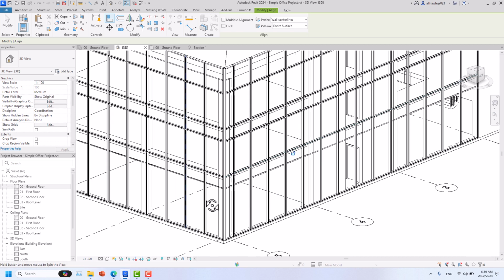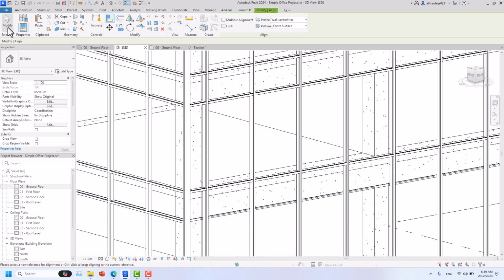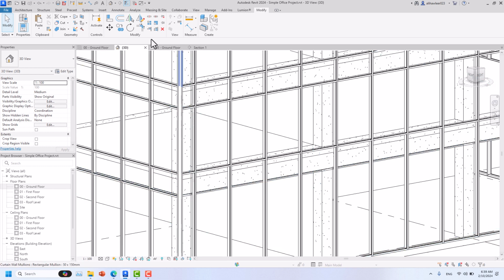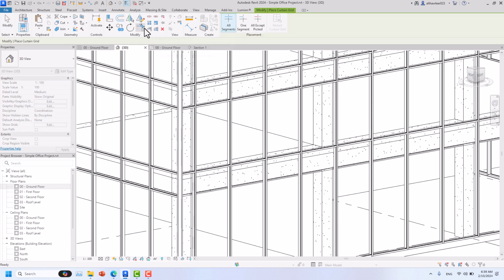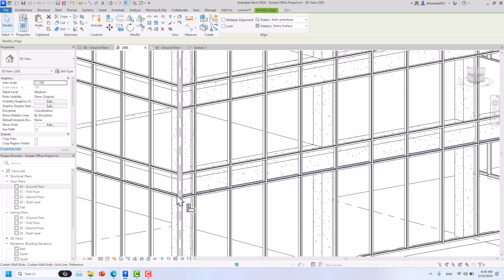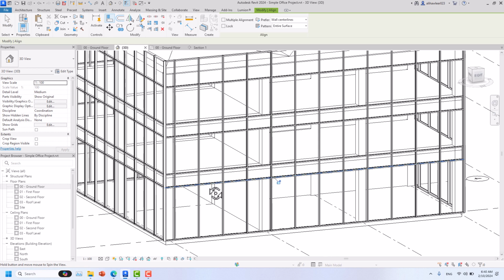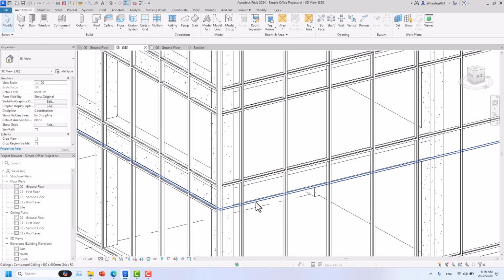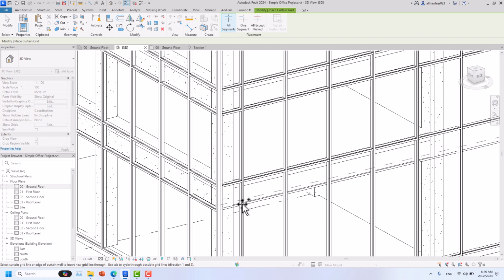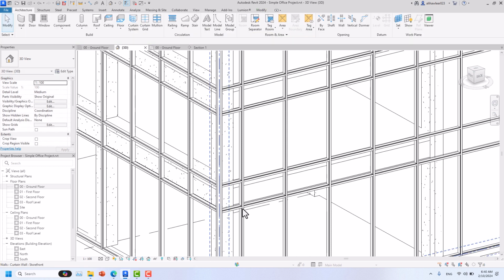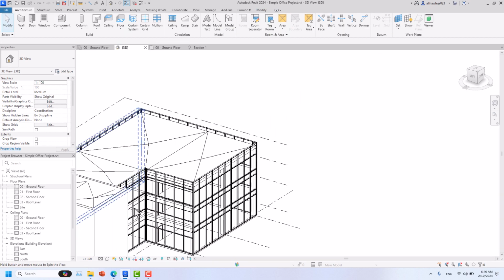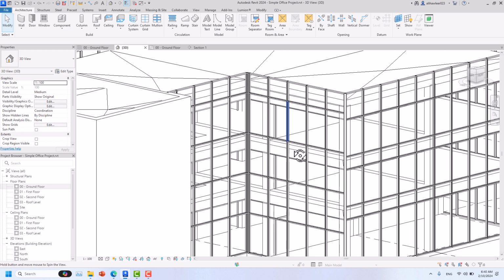with this one. But as you can see, we have a mistake. We didn't add a mullion here. Did you see? So we should add a mullion, or let's say curtain grid. Just go to somewhere here, just align it with this. Okay, you can lock in place it, but this is not what I want. So let me add another one, align it. Okay, and let's see, we have something like this.